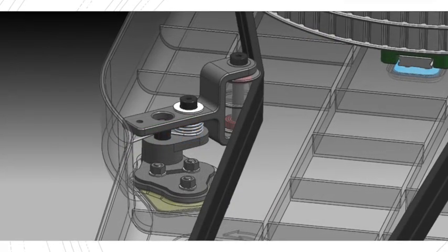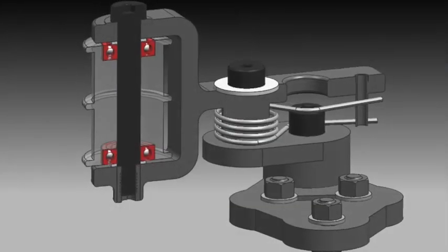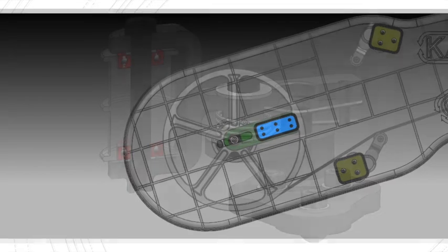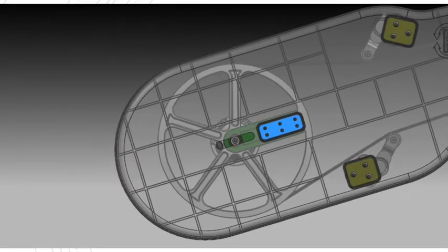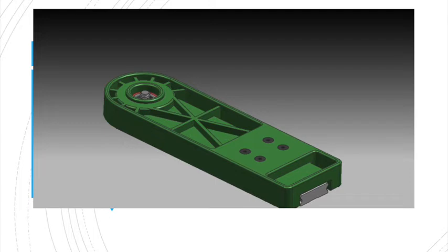This is a close-up view of the belt tensioner on the dual belts. And we have a close-up cross-sectional view of the belt tensioner. This is the ball slide assembly, which enables the changing distance between the wheel gear center line and the turbine center line. The bolt that connects the slide assembly to the wheel gear is shown. The bottom part of the wheel assembly, gray, is bolted to the belt guard.